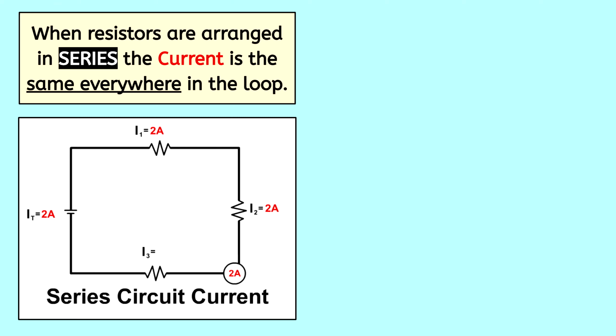We can see there's an ammeter, kind of like the cross arrows moving around in the simulation. The ammeter is moving around the circuit trying to measure what the current flow is everywhere. They go through all the resistors or light bulbs, they even go through the battery or cell, and everywhere they're measuring the same number, which in this case is 2 amps of current. So that's the rule for how current works in a series circuit. It's just the same number everywhere.